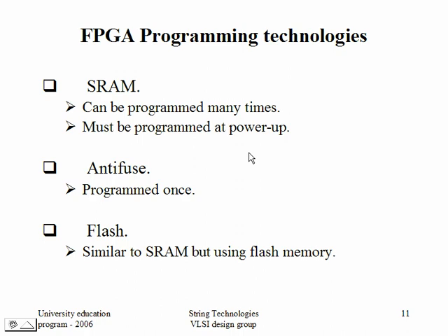That's it. Anti-fuse is the opposite concept. What is opposite? A fuse by default is a closed circuit, and when I want to open it, I have to give a high amount of current. Anti-fuse is the reverse. By default it is an open circuit, and when I want to make the connection, I have to give a high electric field. Got the point? We will see that.